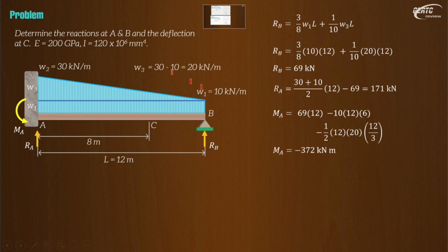And before we proceed for the deflection, by the way, these are the reactions. We have completed the reactions. Now, let's compute ahead our flexural rigidity in kilonewton meter squared. Your E is GPa, and your I is mm to the fourth. So we will use here MPa, so that's 200,000 times I. This will give you Newton millimeter squared. So let's make this kilonewton meter squared. You divide by 1,000 here and 1,000 squared. You divide this by 1,000 to the third power.